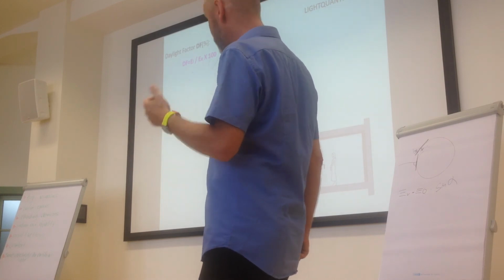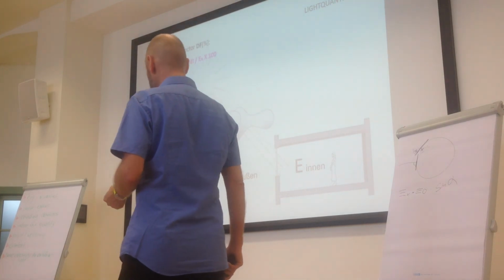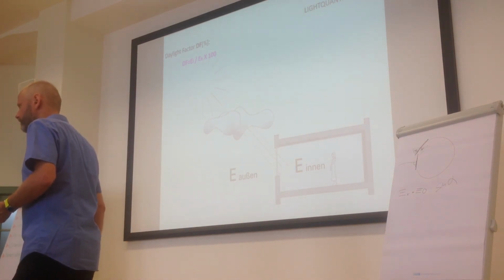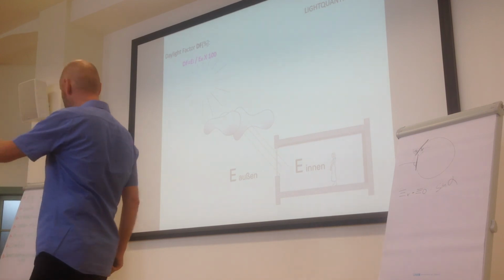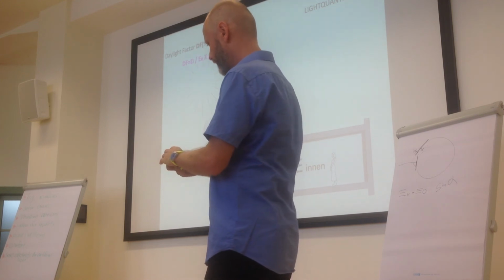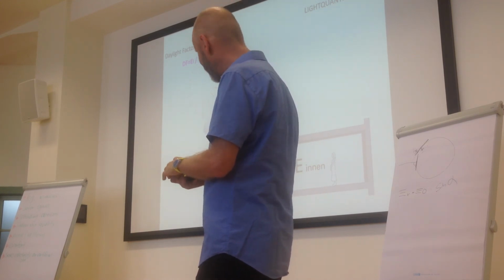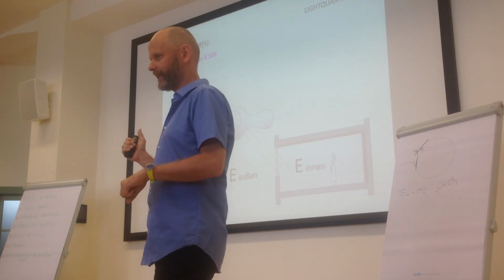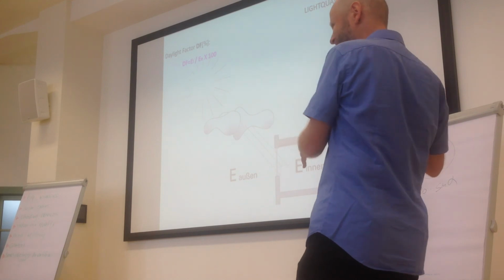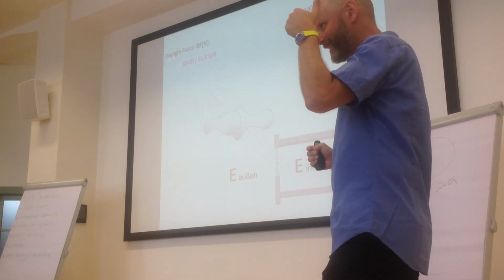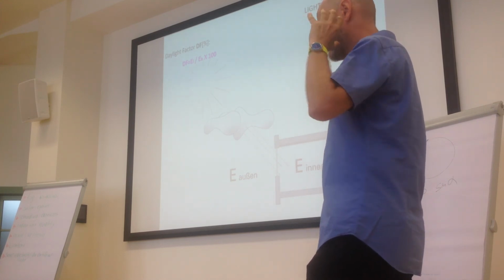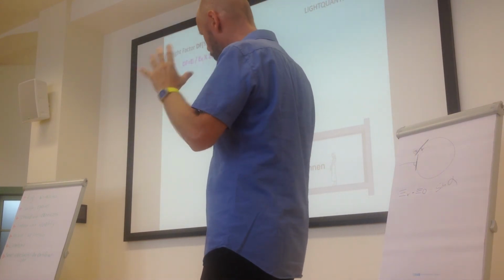And there is a recommendation for daylight factors in interiors. It should actually be 2%. In 2009, the recommendation was a daylight factor of 1%. So 1% of the outside illuminance should occur at the inside. One single percent of the outside illuminance should occur at the inside. This sounds like a very, very low level.